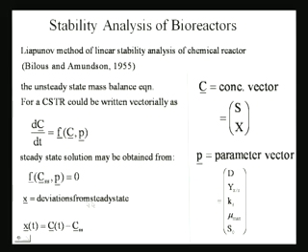Now x is defined as a deviation from the steady state. Why do we define the deviation from the steady state? Because we want to study how this deviation would change as you go away from the steady state. If this deviation is going to increase with time, then the system is unstable. If this deviation x of t is going to decrease with time, then the system is stable. So that is the basic definition. That is what we are aiming towards at all points of time. So x of t, why is it x of t? Because the deviation is a function of time, and we want to study its dynamics as a function of time. So that is written as C vector as a function of time minus the steady state.